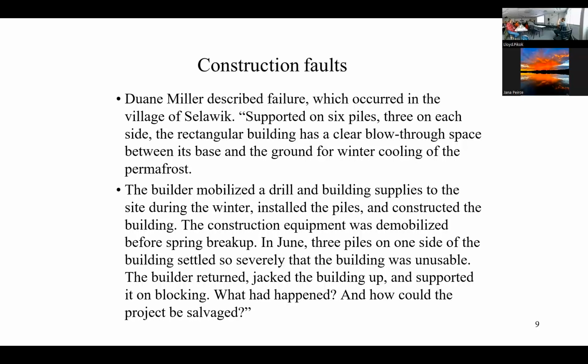But if you look at any classification or requirements for slurry, it's usually said that the slurry temperature, which you put in the hole between pile and permafrost, should be, for some Russian standards, for example, 10 degrees Celsius.